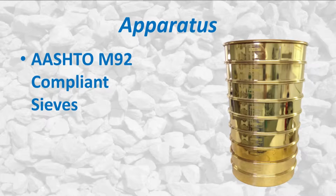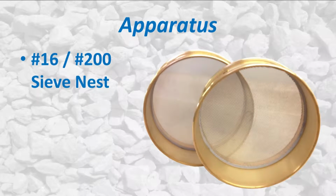Sieves shall be mounted on suitable frames designed not to leak and shall conform to AASHTO M92. A nest of 2 sieves shall be used for this procedure. The bottom sieve shall be a number 200 sieve, and the top sieve shall be a sieve with openings in the range of the number 8 and number 16 sieves. All sieves shall adhere to the M92 specification requirements.